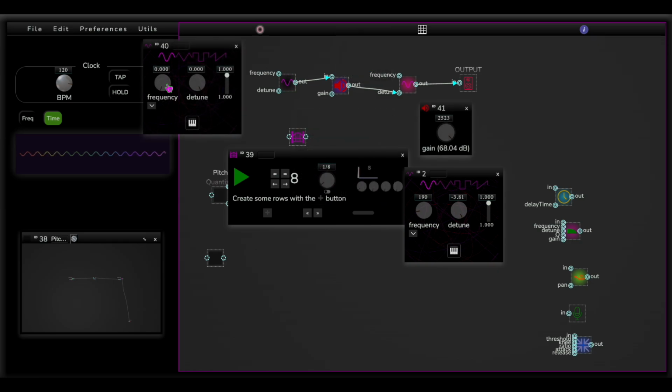Notice that every time I set the frequency of the control oscillator to 0, the pitch changes. That's because setting it to 0 freezes its state, somewhere along the curve. So the idea behind this random pitch technique is to, very briefly, increase then decrease the frequency of that oscillator. We can use an oscillator and a gate sequencer to achieve this.